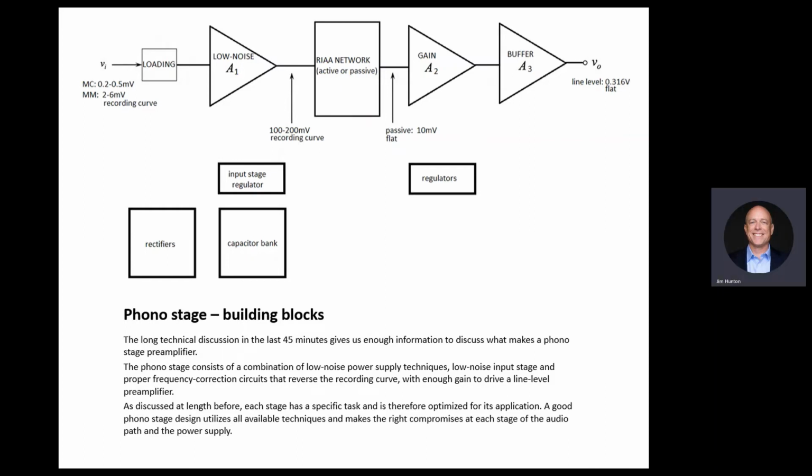So we get to this point with the first level. I'm just giving an example of the one unit that we have, but a lot of units follow the same concept. You get a gain from 5 millivolts up to 100 millivolts, a gain of 20, sort of. Then you use an active or passive RIAA network. You may have a low pass on this circuit in the beginning and several other stages that form the RIAA.